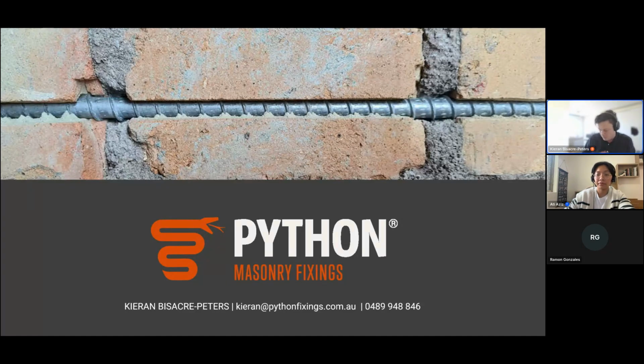Yep. So we have solutions for lintels, whether they're concrete or brick lintels. There's been situations with concrete lintels where all the bars have been corroded, they've removed it, installed some of our anchors into the brickwork, and then cast the concrete over the heads of the anchors. There's also the products for crack stitching out there. We have one of these. They're sometimes used for strengthening lintels as well by laying the steel wire rope along the lintel to act as a sort of tension reinforcement of a beam. So there's various methodologies for strengthening lintels.